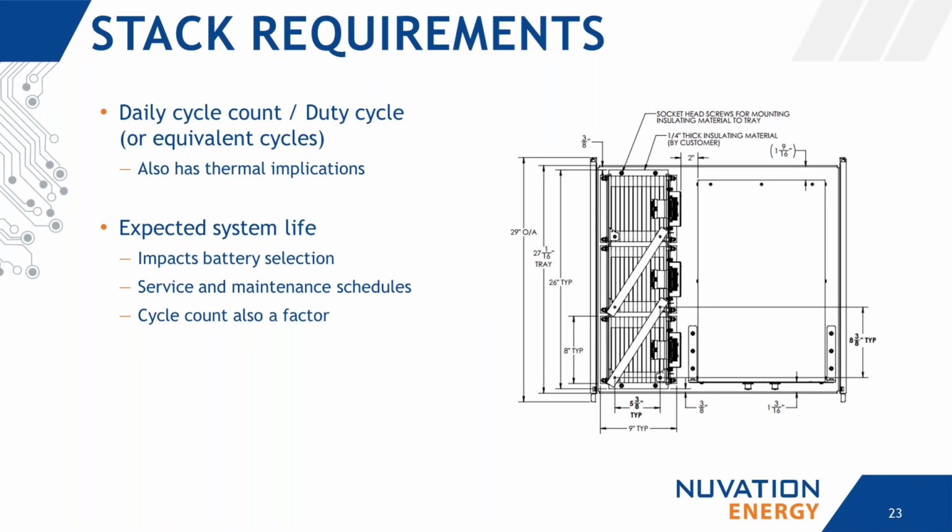Next, we have to consider the daily cycle count, or for applications where cycles are not necessarily straightforward, it's the equivalent cycle counts that we care about. This impacts the thermal management requirements depending on the duration and frequency of rest periods. Said another way, the duty cycle of the system.